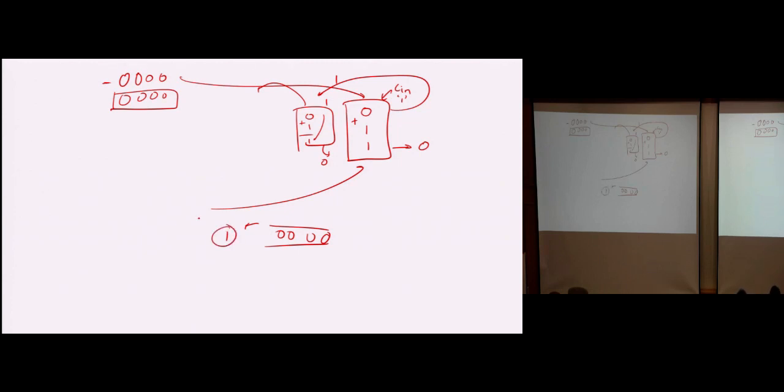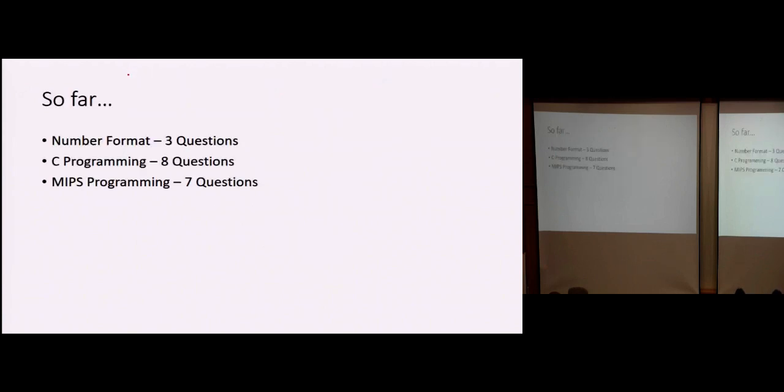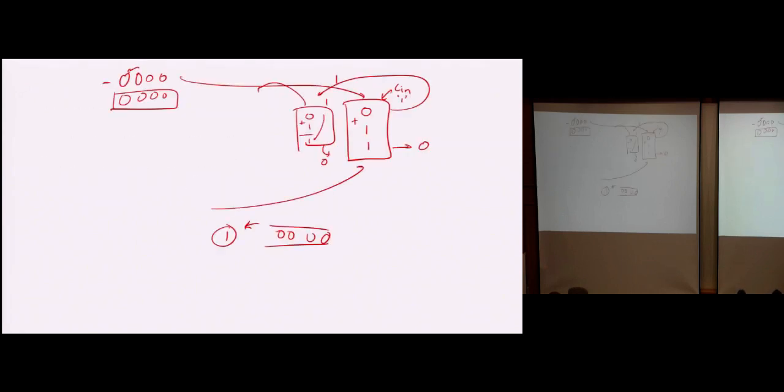It's up to us to see whether the processor will look at it and trigger it as an overflow condition or carry out or whatever. In some processors there are certain flags to indicate whether it's a carry or overflow. We have not covered this yet, but basically in this case, the carry in to the most significant bit will be 1, and the carry out will also be 1. So in this case, there is no overflow condition.